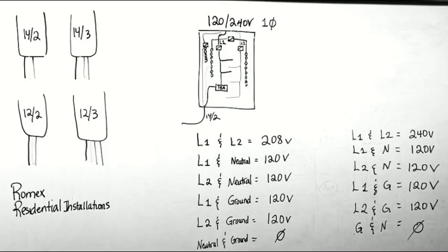Okay? So you guys have a table. If I ask you what is the amp capacity of a number 10, or what's the amp capacity of a number 8, you should be able to find it in your table, and it tells you what's the amp capacity of a wire. So all of this information is out there for you to know what size of wire you're going to use. Okay, so this one right here is a number 8.